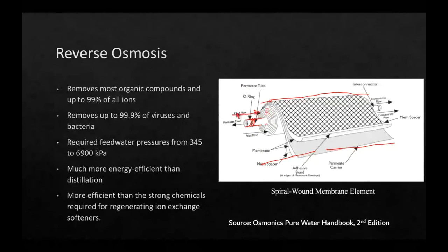Due to the high pressure here, this high pressure feed, we overcome the osmotic pressure. We end up forcing the permeate into this perforated pipe that runs the length of it. So the permeate comes through and goes off to the boiler. Actually, it's going to go to the deaerator. It's going to be makeup, but I'm just going to say boiler anyway. And then what comes from this membrane area at the other end is the concentrate. And there you go. That's all I have to say about reverse osmosis.